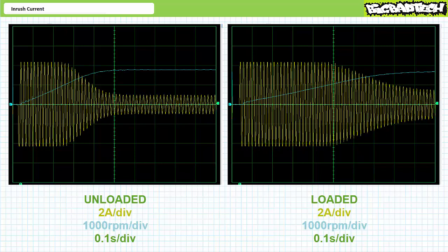This is meant to imply that the starting condition of the motor can affect inrush magnitude and duration. It's this same phenomenon that also explains why motors overload when they're single-phased at standstill. If the rotating magnetic field is never established, the rotor doesn't move and no counter-electromotive force is produced, and as a result, the motor experiences a sustained inrush condition.